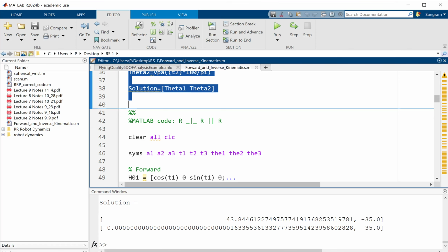What you have is the 4-bar mechanism, which is actually acting like a link. But the logic remains the same. We don't worry about how the robot is physically constructed. For example, the shoulder joint is a spherical joint, but for us, this joint is nothing but 3 revolute joints attached perpendicular to each other, but coinciding. You would actually separate that.